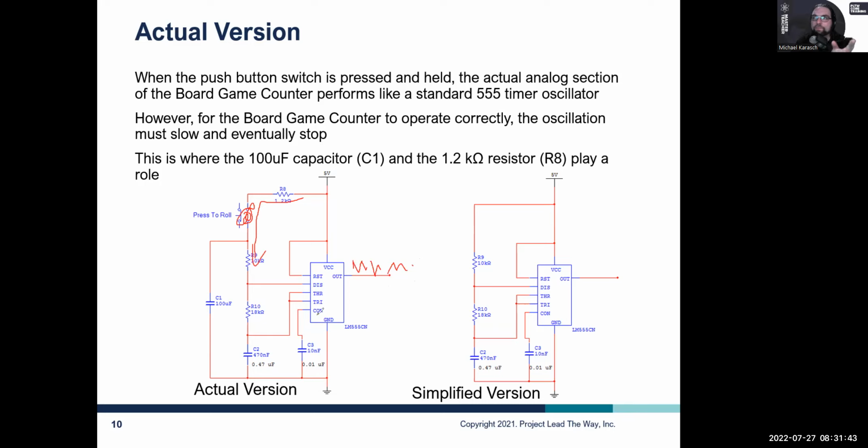Everything's great. But while it's doing that, we have this capacitor over here that's in parallel. So quietly, without really affecting this circuit, this capacitor is filling up. It's filling up, and eventually it gets totally full. And a capacitor that's totally full basically acts like a break in the wire. So when this capacitor is totally full, it's like it doesn't even exist. The circuit doesn't even know it's there. But it's been charging its battery over there, so to speak. It's a big full tank of voltage. Okay.